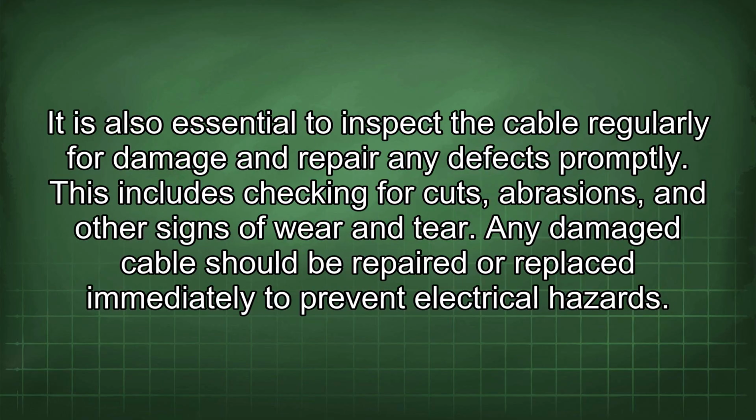It is also essential to inspect the cable regularly for damage and repair any defects promptly. This includes checking for cuts, abrasions, and other signs of wear and tear. Any damaged cable should be repaired or replaced immediately to prevent electrical hazards.